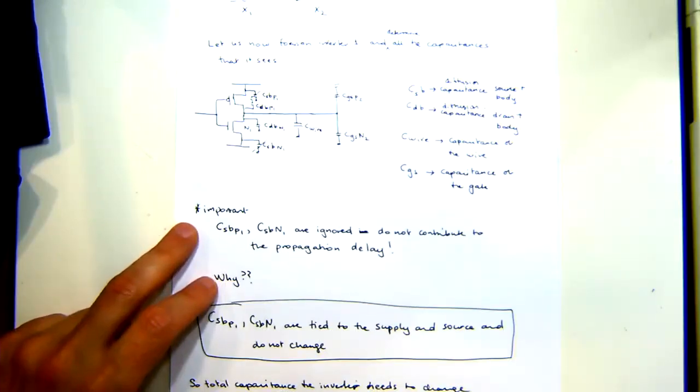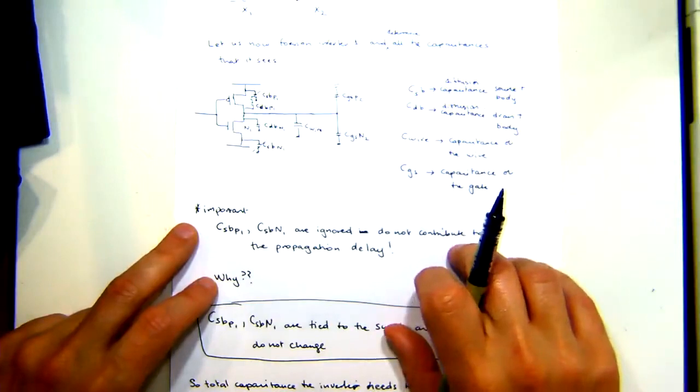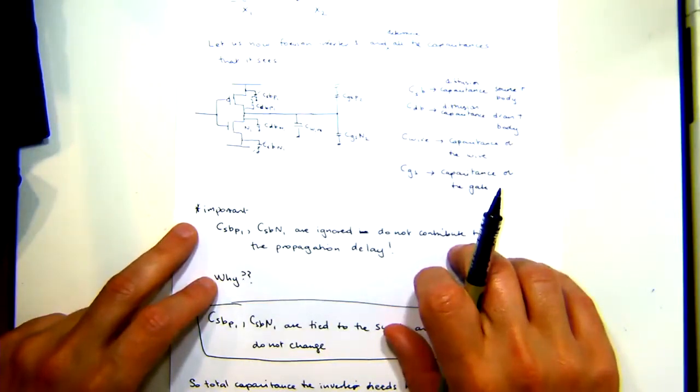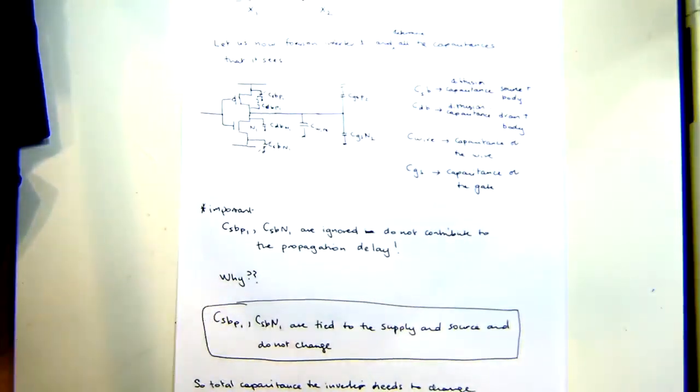So usually, I think on the 65 nanometer Samsung process, 50 micron is the minimum. To do what? Sorry. The top layer, the RF layer. Width. I don't know. Okay, but usually it's quite large, right? And therefore you've got a bit of a trade-off, right?